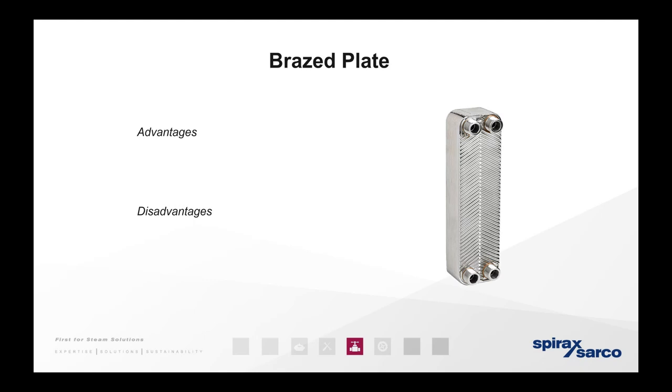So I'm trying to think, are they talking about the transfer of the heat between the primary and the secondary, or just the mechanical mechanism of how a heat exchanger works? I think it's just around how a heat exchanger works in terms of pressure drop across the plates. Yeah, so in every steam system, even a heat exchanger or any piece of equipment, you need a pressure differential across it because you need to have flow. So that gives you your flow.